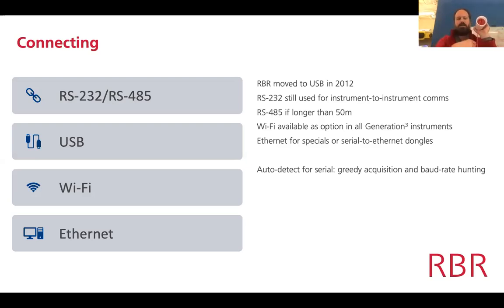However, with the standard instruments, we also have a second port in here, and that exposes RS-232 and 485. Although we moved to USB as the standard desktop connection about 8-9 years ago, RS-232 and 485 are still necessary for underwater connections to other bits of equipment. It might be talking to the float or the glider. It might be talking to an underwater Campbell logger that you want to move the data to. And so RS-232 for up to 50 meters and 485 for much longer. We've made 485 cables, I think, about 500 meters in length.